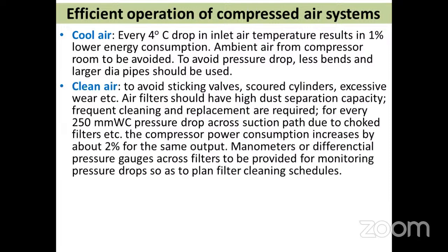Clean air is also important, because of the filters there will be increased power consumption, sir. So you need to clean the filters frequently, and you'll be using manometers for measuring the pressure across the filters to clean them frequently.